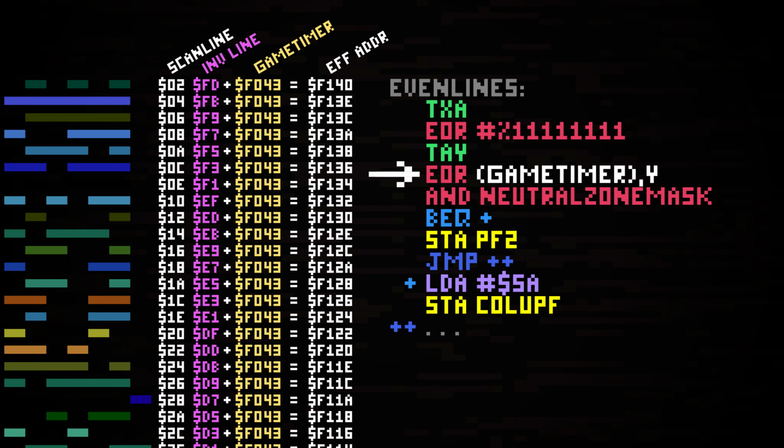This also causes another interesting pattern in the neutral zone if you look close enough. Since the even lines and the odd lines read from the same ROM area, but one is just a reversed copy of the other, if you ignore the colors, the neutral zone is symmetrical vertically at the 128th scan line. The sequence of 128 ROM values that can show up as part of the neutral zone changes every frame, but each time it's symmetric, which means even as it animates, it has this reflection point about 2/3 of the way down the screen.